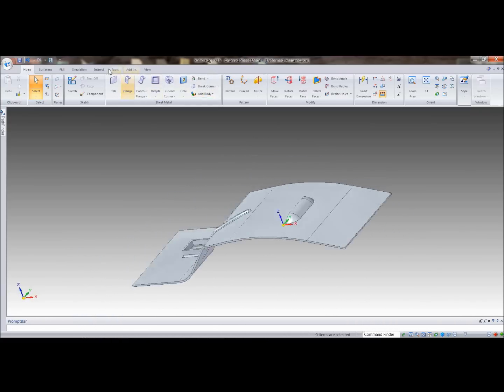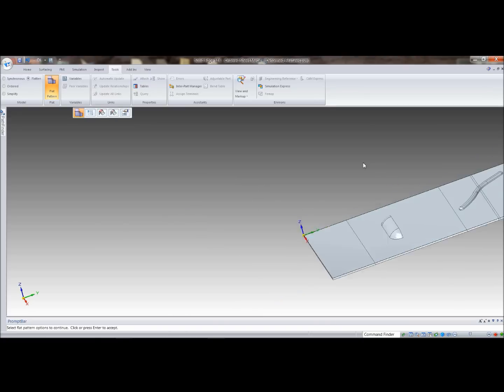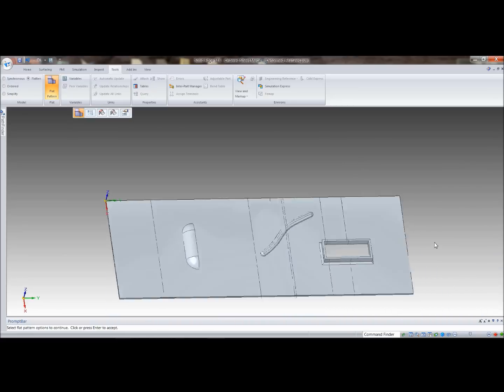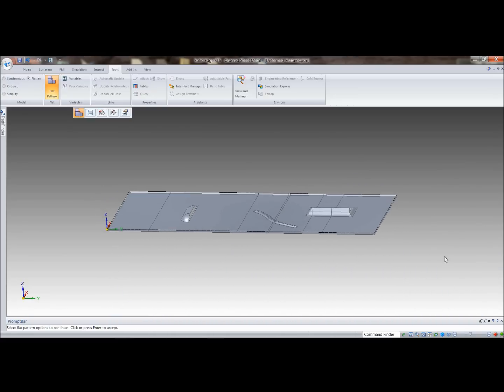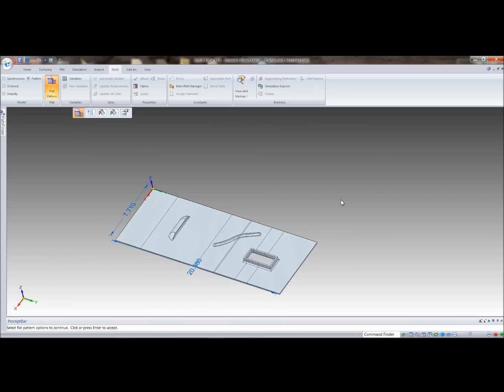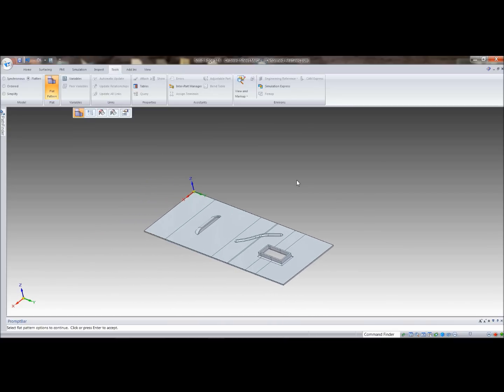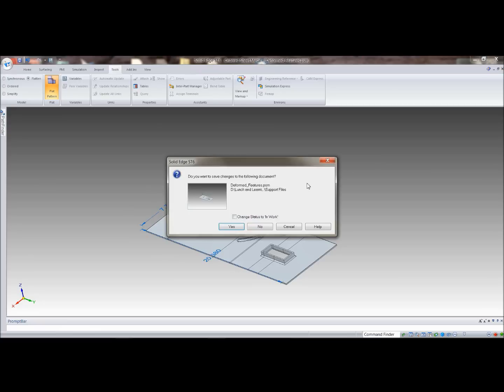And again, the flat pattern, let's make sure that that works. So create your flat pattern so that you have placement for the locations for those deformed features. And you can go ahead and create the 2D drafting for that, or the DXF file for sheet metal folks to make their thing, get their part of it done. So very nice enhancement.